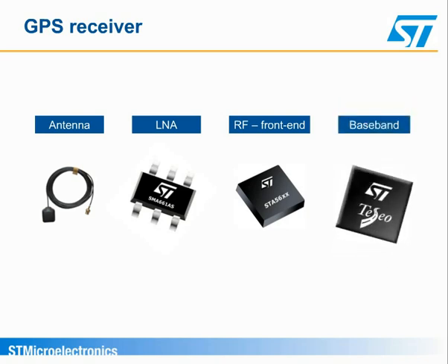The digital signal is forwarded to the baseband circuit, which contains all the correlators, PRN generators, and logic to decode the satellite signal. The baseband device also contains a powerful CPU to calculate the equations introduced and determine the actual position in a longitude-latitude system.